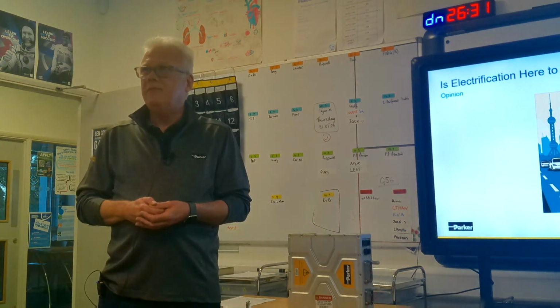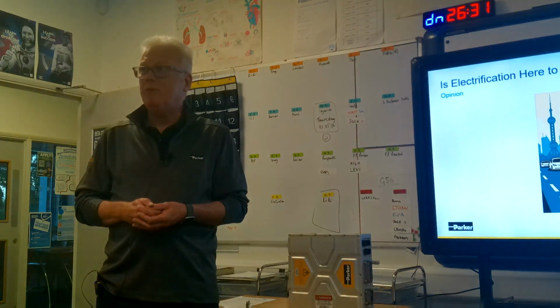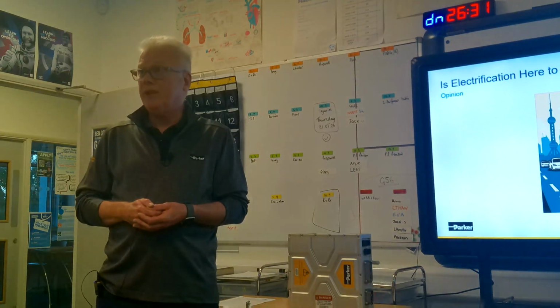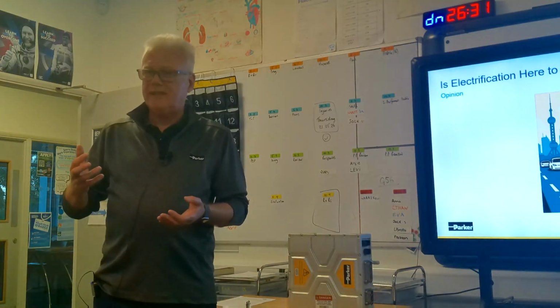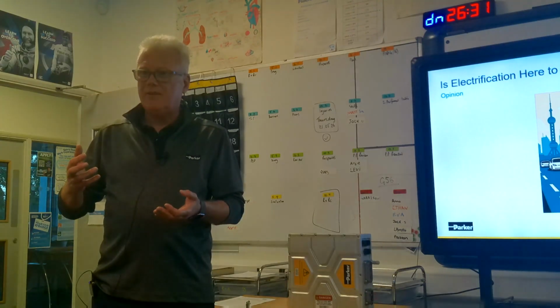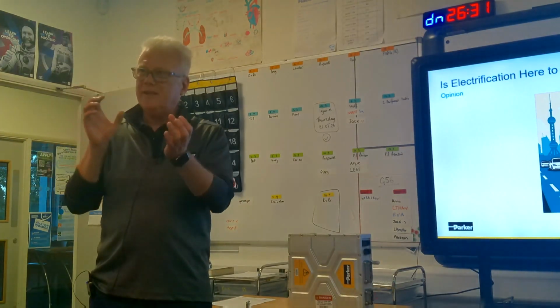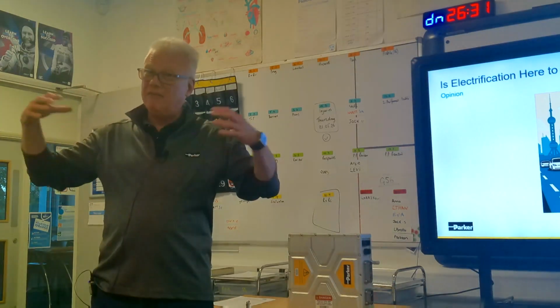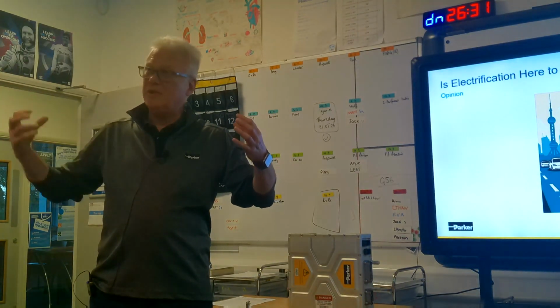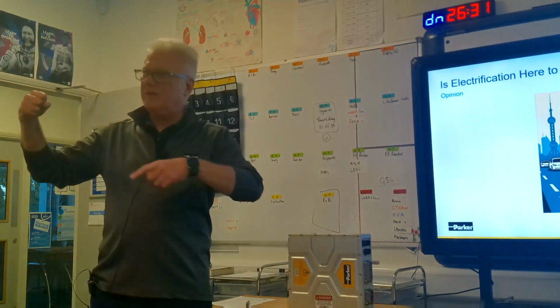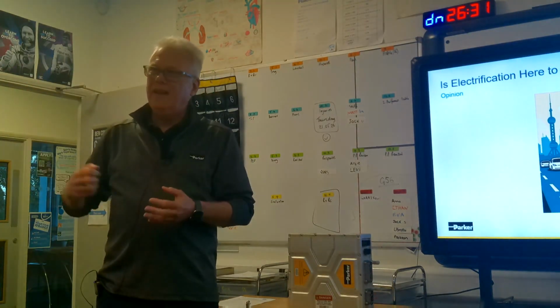There's lots of research at the moment, especially in aerospace applications, where people are trying to make fault-tolerant machines. I've seen a couple of examples of this now, where effectively you try and build 4 motor windings in one machine and have 4 inverters. And the idea would be, if there was a failure in one, you'd somehow contain the fault in one, but the other 3 could keep the thing limping on.